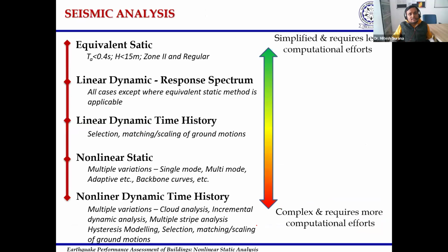Now coming to seismic analysis. As you may be familiar, there are a variety of seismic analyses that are recommended in building codes. For example, the first and the simplest method that we use in our analysis for earthquake forces is called the equivalent static method, which is based on the assumption that the response of the structure is governed by a single mode of vibration. When we talk about the response of a structure governed by a single mode of vibration, that means the structure is low rise. So the fundamental mode is well enough to capture the response of the structure. That is the inherent assumption involved in equivalent static analysis.